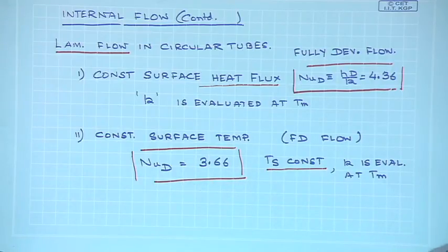So, if I can express this friction factor F as a function of Reynolds number, then it would be easier for me to extend this result for the case of heat transfer as well. So, for the turbulent flow inside a pipe, we have to use the analogy between heat transfer and momentum transfer, and knowing the expression of F from Moody diagram, I should be able to obtain an expression of Nusselt number. That is how we treat turbulent flow in a pipe, in a tube, when we are experiencing heat transfer in turbulent flow.